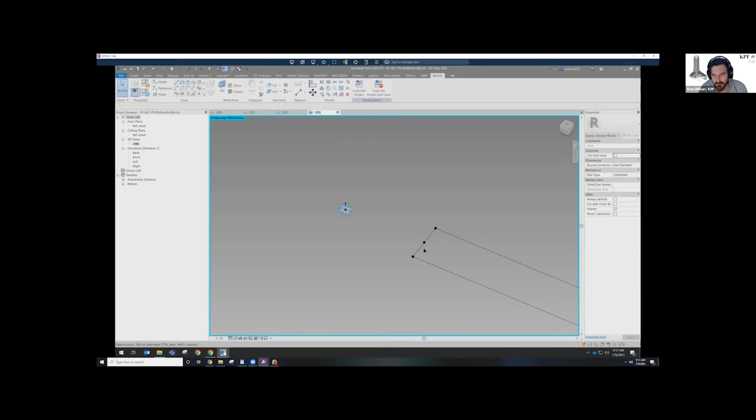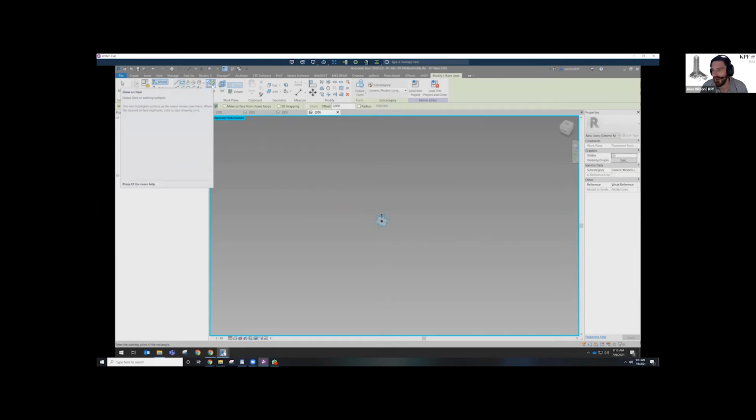So, why don't I just delete this? And at this point, you can just sketch. So I've set my work plane. Now the next step is seeing where it's actually going to snap to. There are two options. One is draw and face. If you already have some geometry set up, it'll just automatically snap. We actually want to draw on the work plane itself. A profile, obviously, you don't want it to snap off into random locations. So we're going to select that. And then you can just use a 2-point box, something like that, to get your profile.